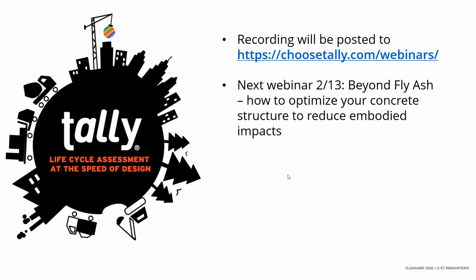We have another question about when I mentioned in Tally, why is it capable of comparing across different product categories? Obviously you do want to make sure that you're comparing something that's performing the same functional purpose, but that's from an LCA perspective, and it does allow you to compare across things that actually come from different product category rules. I think I mentioned a flooring example of, say, carpet versus polished concrete. There's going to be very different product category rules for those two things, but the virtue of Tally, by having a single database produced by a single software by a single entity using the same assumptions, allows for those types of comparisons. And similarly, say, a wood versus steel structure, where there's very different information that goes into generating the background data. If you were to compare EPDs, they could be wildly divergent, but they wouldn't be in the context of Tally.